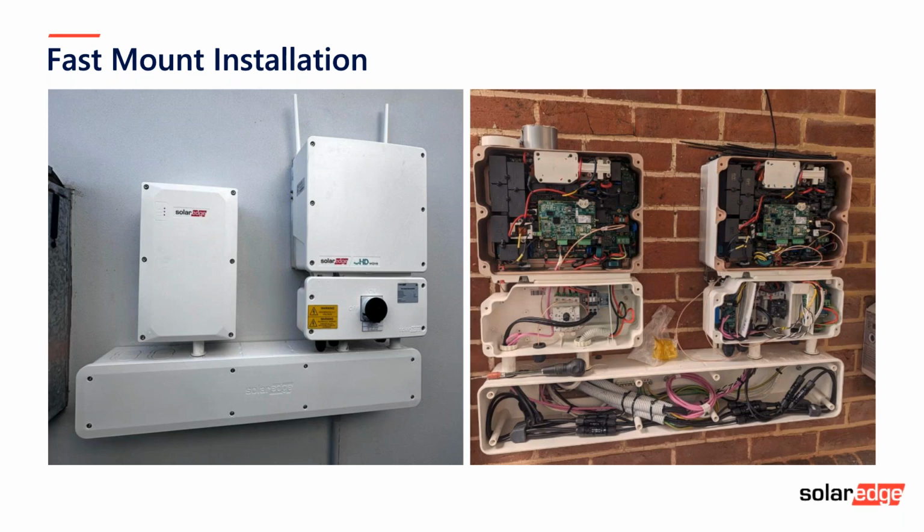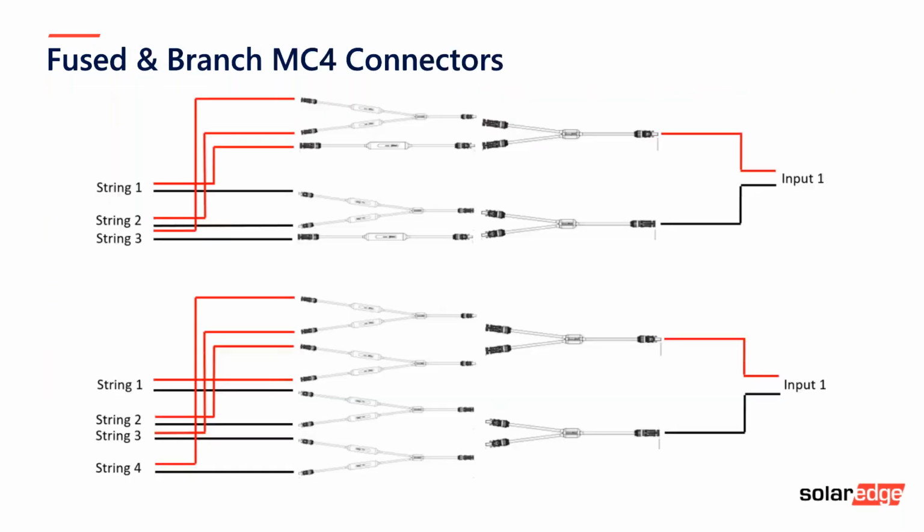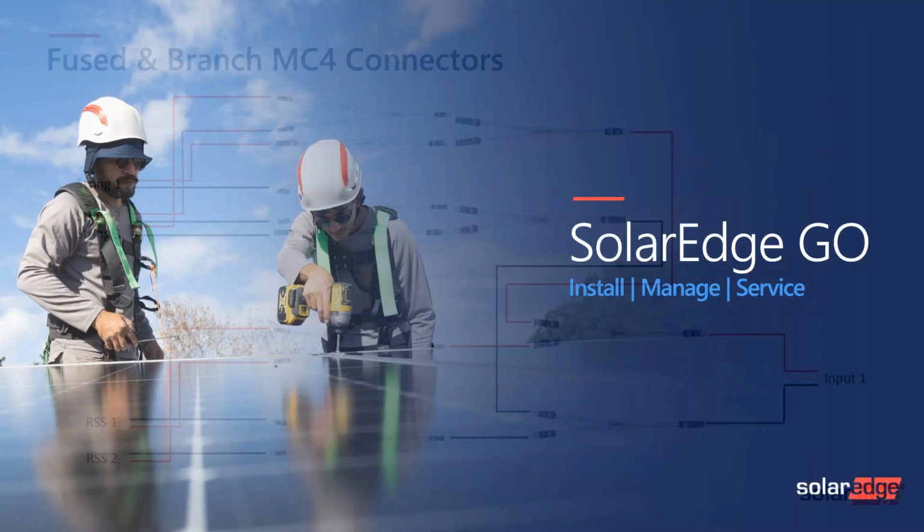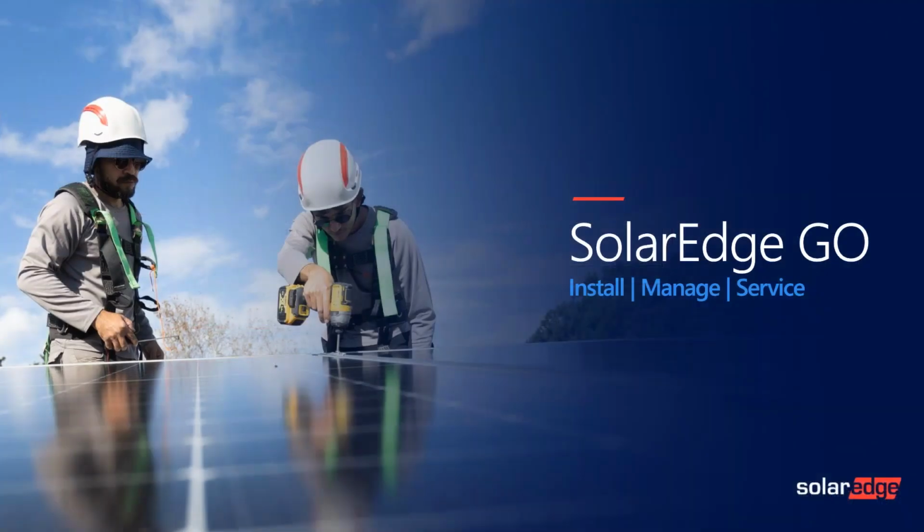We're hoping to get those released towards the end of this year, as well as a slightly different range of our existing branch connectors, ones with fuses in it, to help with systems where you've got lovely amount of oversizing, where there may be 3 or more strings where you need to have overcurrent protection, which looks like this. So these are some illustrations here to show you how the fused branch connectors work to be able to combine your strings. And then also if you've got multi-strings and multiple batteries, how you can bring everything together into the single input into the inverter using fused connectors or non-fused connectors if need be. They should be with us again about the same time as the fast mount.